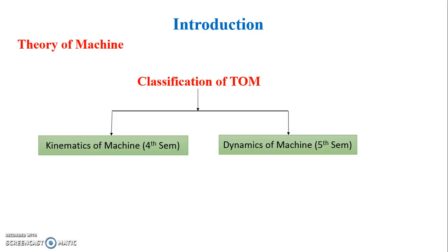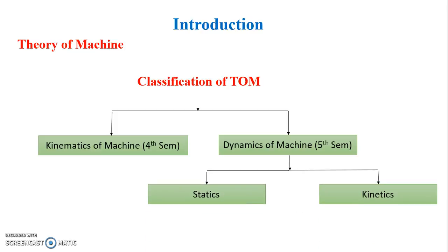Again, this dynamics of machine is subclassified into statics and kinetics. Statics deals with the forces and their effects while the machine parts are at rest. Kinetics deals with the inertia forces which arise from the combined effect of the mass and the motion of the machine parts.